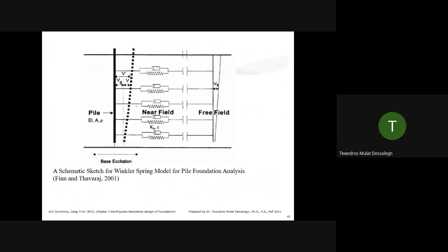So this is what it does, that PY approach, series of springs. Now what we do is we just reduce the spring resistance by about 80% to account for liquefaction. This is like a pseudo-static approach. But if you do purely a dynamic analysis in FLAC, you'll automatically get it, which is an even more realistic approach. But it's also costly and time-taking. But you can do it both ways and compare it. You have a pseudo-static approach and then do a full dynamic analysis.